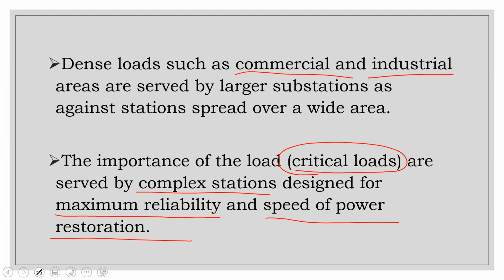What are some of the other considerations as it relates to load and voltage and space? Right? We have to bear in mind that we're going to have growth in load, but growth in what type of load? So I suppose when we talk about load growth, persons are going to say, well, you know, yes, they must have had capacity there for increased load. So if a man puts up, even a tire shop where he's running his compressor, the compressor puts reactive loads on the system because he's now running motors.